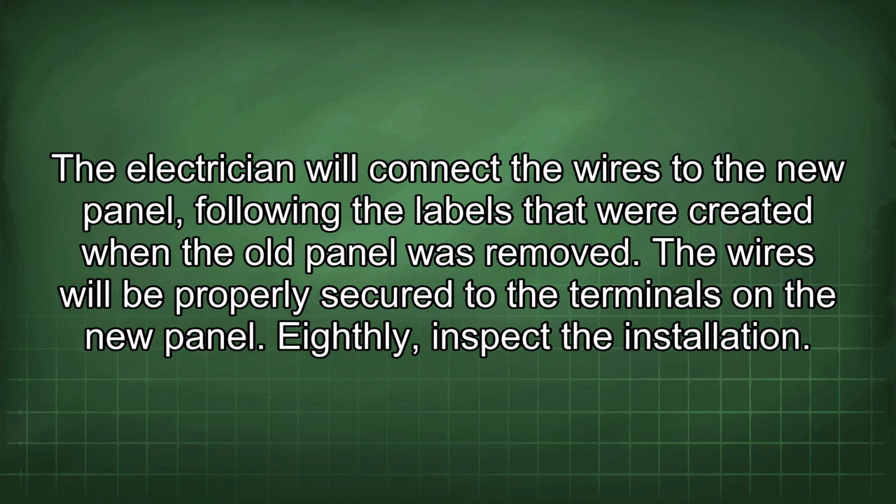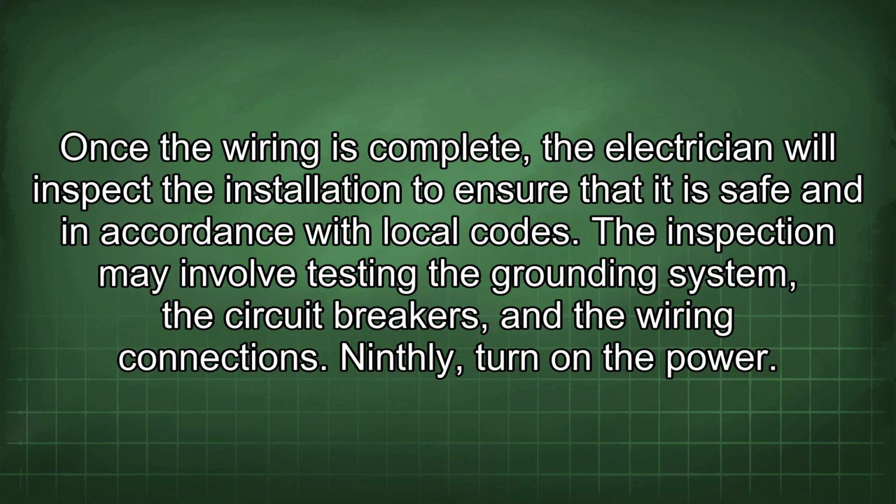Eighthly, inspect the installation. Once the wiring is complete, the electrician will inspect the installation to ensure that it is safe and in accordance with local codes. The inspection may involve testing the grounding system, the circuit breakers, and the wiring connections.